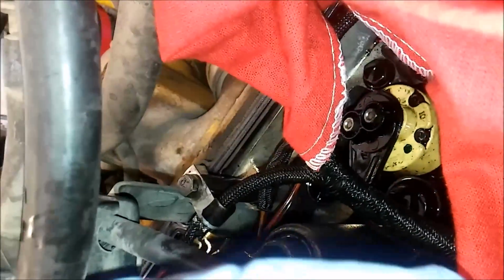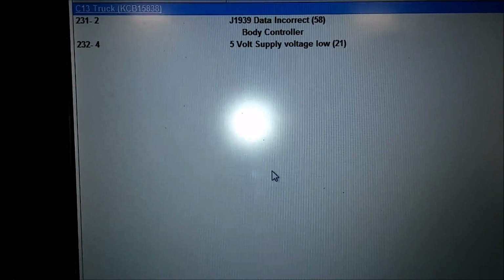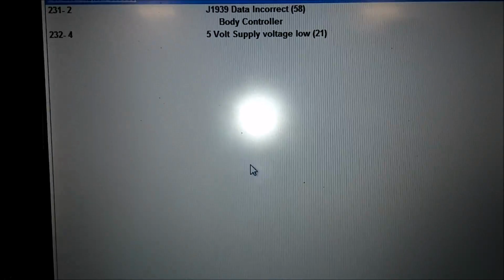So basically, at this point, you do need a new sensor. Now, if you swap those around, you're going to get another code. It's going to say supply voltage low. That's because you're not going from the return to the sensing voltage. You're going from the sensor supply voltage to the return. So that's also a good thing because you've just shorted that, and the ECM is picking up a fault on that circuit as well. So that's really most of the troubleshooting on these sensors, is basically shorting them and then making sure that the ECM picks up on it.